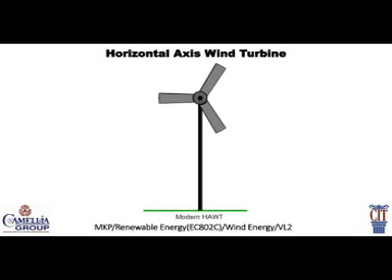As the rotational speed of the wind turbine varies with variation of wind pressure, modern wind turbines use solid state converters to convert the generated electrical energy to the required voltage level and frequency to feed the electrical grids. No one can control the wind pressure on the blades by any means.